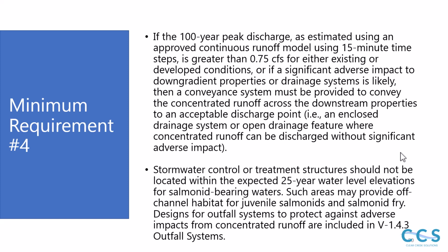Stormwater control or treatment structures should not be located within the expected 25-year water level elevations for salmonid-bearing waters. Such areas may provide off-channel habitat for juvenile salmonids and salmonid fry. Designs for outfall systems to protect against adverse impacts from concentrated runoff are included in 5-143 outfall systems.